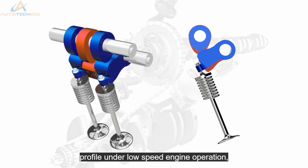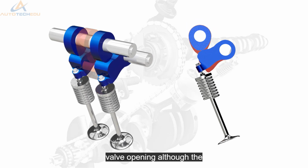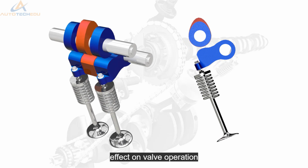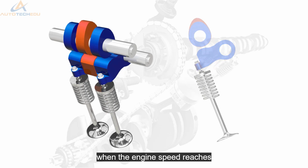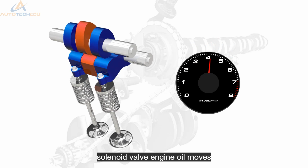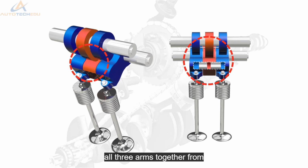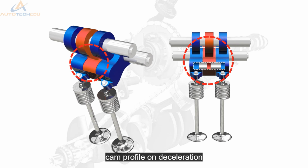Under low-speed engine operation, only the outer arms control valve opening. Although the centre rocker arm follows its cam profile, it does not have an effect on valve operation. When the engine speed reaches a predetermined point, the ECM controls a solenoid valve. Engine oil moves a shuttle pin to lock all 3 arms together. From this point on, the rocker arms follow the more aggressive cam profile.